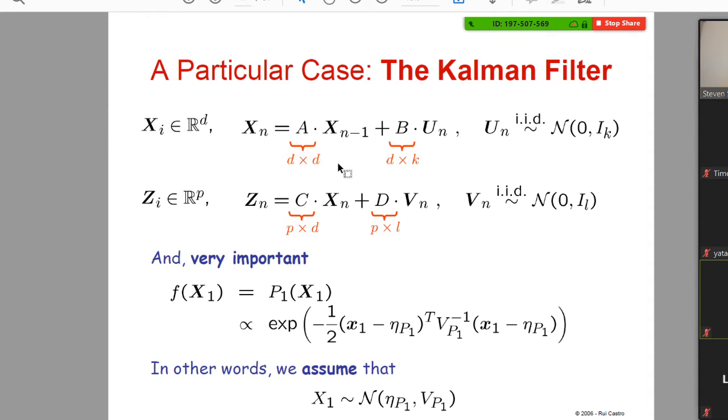I'm not sure you know about the state space model. If you have learned some basic linear theory, normally we use a difference equation or differential equation to describe a system, but we can also use a group of differential equations or difference equations to describe the system. Normally it's first order difference or differential equations. They can describe the system. This is called a state space model.